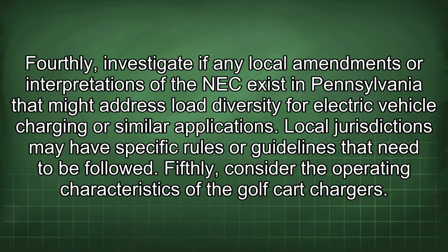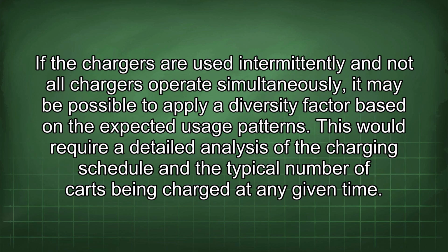Fourthly, investigate if any local amendments or interpretations of the NEC exist in Pennsylvania that might address load diversity for electric vehicle charging or similar applications. Local jurisdictions may have specific rules or guidelines that need to be followed. Fifthly, consider the operating characteristics of the golf cart chargers. If the chargers are used intermittently and not all chargers operate simultaneously, it may be possible to apply a diversity factor based on the expected usage patterns. This would require a detailed analysis of the charging schedule and the typical number of carts being charged at any given time.